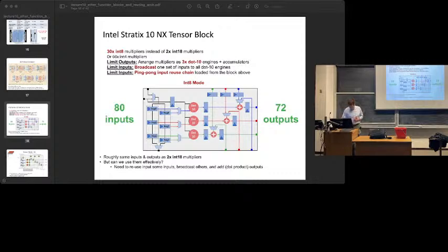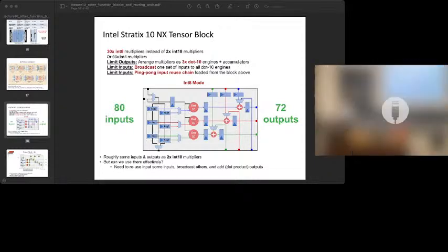So the first thing they did is they arranged their multipliers not as 30 independent multipliers, but as 3 dot product units. Each dot product does 10 multiplies and accumulates the results and produces 1 output. So that's how they solved their output problem. They don't have 30 outputs. They have 3 because they force you to use them as dot product units. Does it make sense? If you didn't want dot product, then don't buy this chip, right? Because it's not going to be very good at it. But that doesn't solve their input problem, right? So the dot product units would still need those 480 inputs.